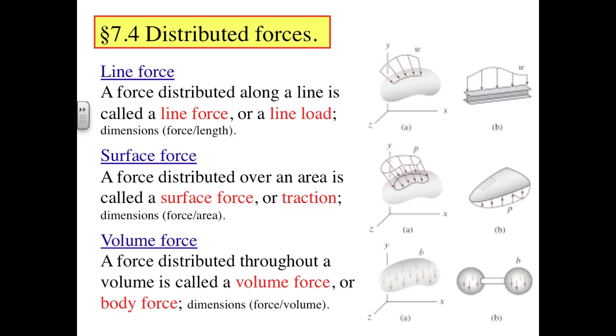We also have body or volumetric loads, the most common being due to gravity. Here the distributed load is volumetric mass density ρ times gravitational constant g. Integrating over the body's volume gives us the weight as the integral over the volume of mass density times g dV. Line loads are not so much physical as constructions from surface or body loads for specific applications.